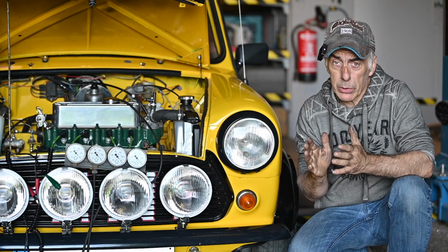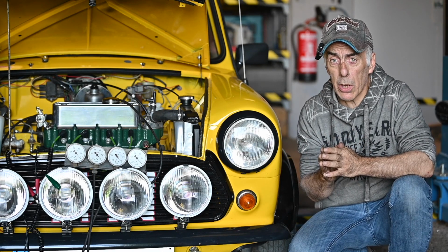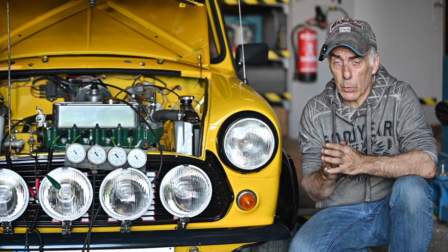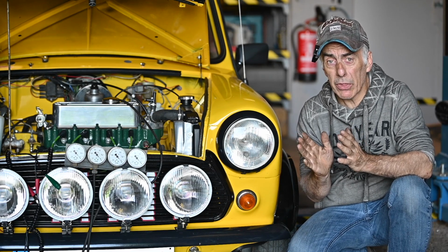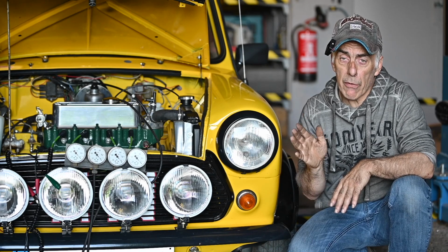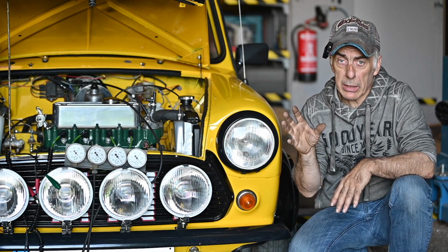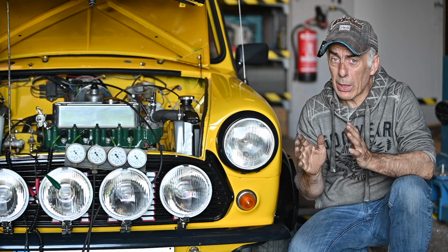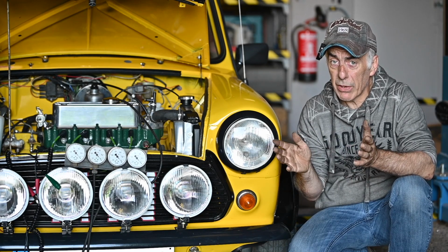It may be different on your car, but there are always markers on your vehicle where top dead center is, and these are the ones you need to check. Now, I have to say one thing. You can't always trust the markings on a cover that's fitted to protect the distribution chain or something like that. The pointers are not always right, and quite often it can be off by 3, 4, 5, and even more degrees.